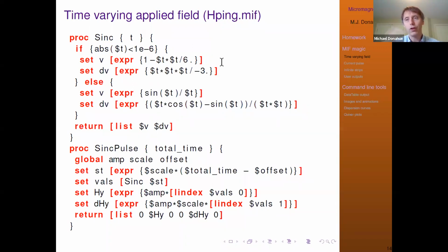You have to be concerned in the Fourier transform space, the FFT, that you're going to get aliasing from the higher frequencies. And also it's flat across the frequency range of interest, so you don't have to worry about scaling for the excitation.